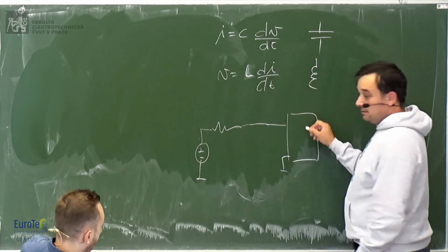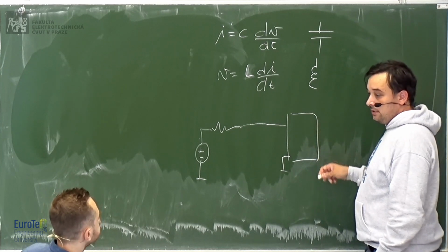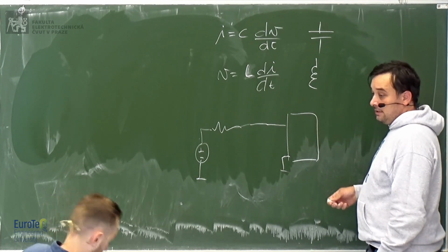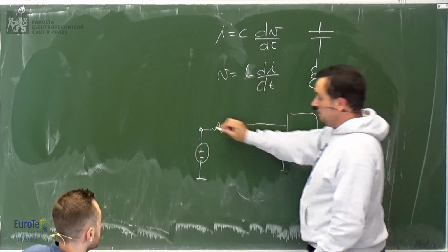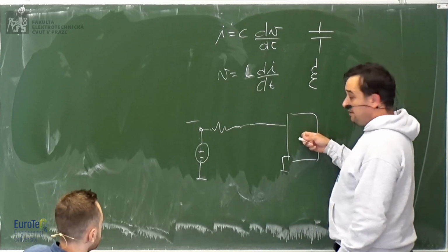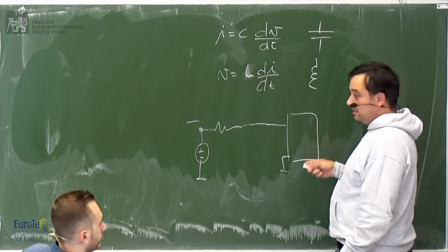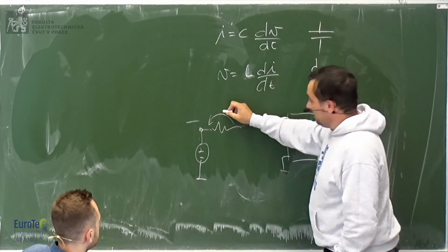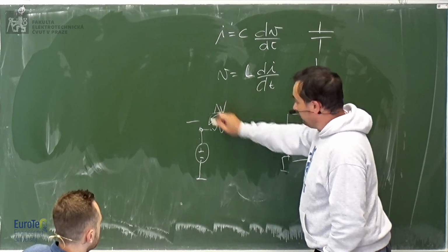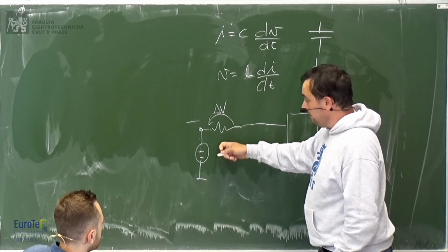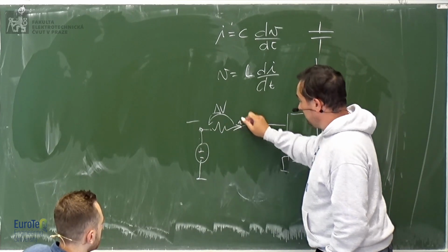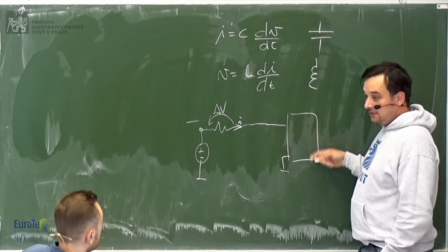Maybe this device absorbs some high frequency, because here you have a source of voltage which is very nice, flat and smooth, but this device has a bunch of things switching inside. Then you get some voltage drop, which is given by the current, which also carries this frequency.